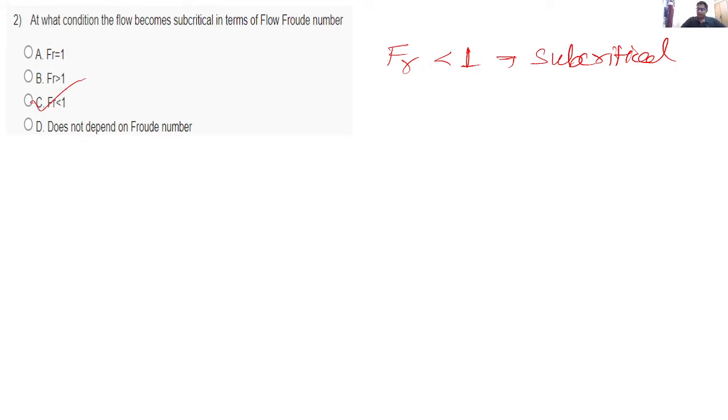Now, some basics about the Froude number. Froude number basically describes the flow regimes of open channel flow. It is nothing but the ratio of inertial to gravitational forces. Now, let us suppose Fg is gravity force. It would tend to move the particle downwards. Whereas inertial force, let us denote it using Fi, will indicate whether the particle is willing to move downhill, or the heaviness of the particle is represented by the inertial force.